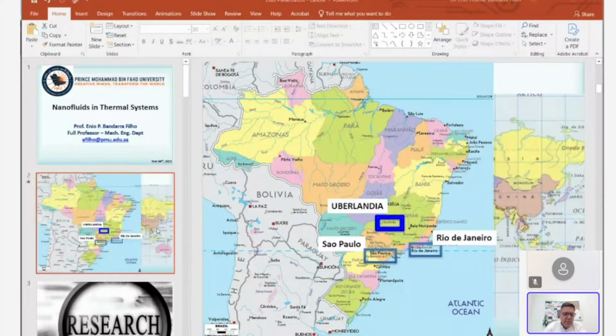As you can see, here is about concentration. The red one is the lower concentration, then the average concentration, and the purple one is the highest concentration. You can reach average improvements of around 90%. These nanoparticles are silver with 20 nanometers of diameter, basically. If you increase the diameter of the nanoparticle to 80, for example, you can sometimes increase the thermal conductivity increment, as you can see here.